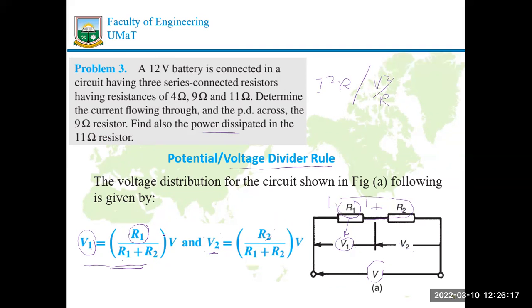And not forgetting there's the first one, I didn't say it. You should multiply by the overall voltage you have across that set of resistors. And usually this principle works when you are looking at a series circuit or you are looking at a part of a circuit, all right? It can be a branch part of a circuit that has some resistors in series that you need to find the individual voltage drops across those resistors that are in series.